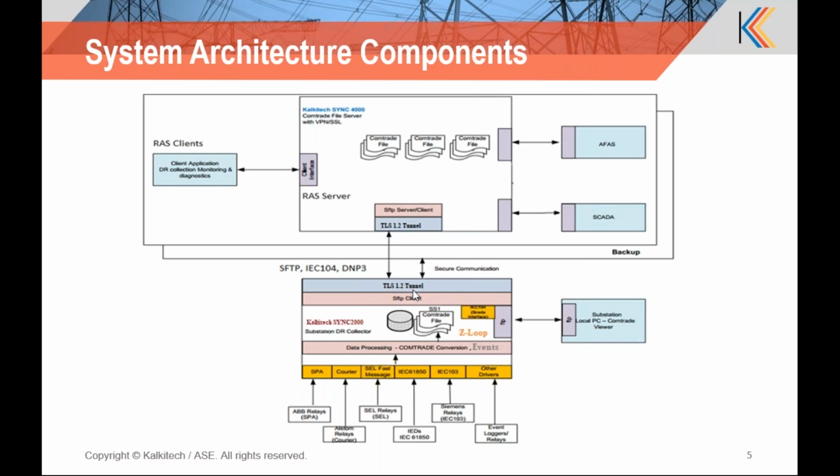Plus, this impedance value is available to map to the corresponding protocols like 104 and DNP3, and the same value is sent to the center to do the complete analysis. So these complete loop impedance values are available and pushed to the central system for analysis.